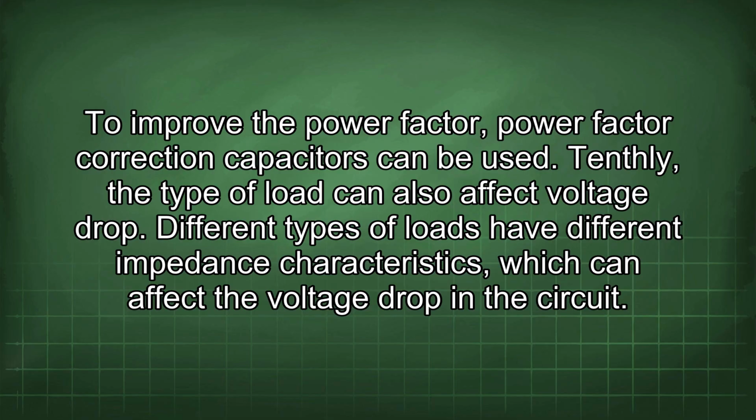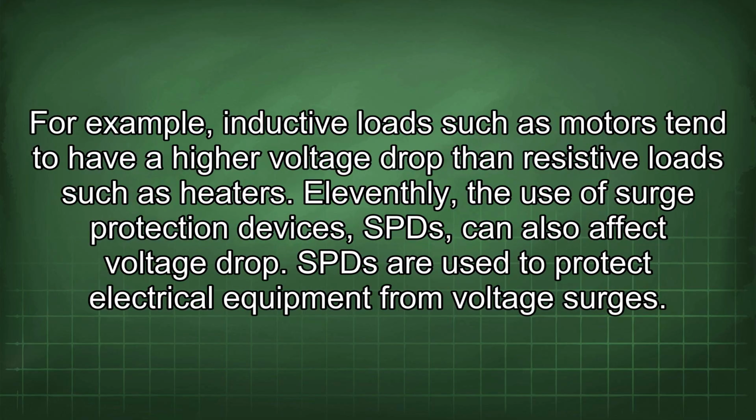Tenthly, the type of load can also affect voltage drop. Different types of loads have different impedance characteristics, which could affect the voltage drop in the circuit. For example, inductive loads such as motors tend to have a higher voltage drop than resistive loads such as heaters.